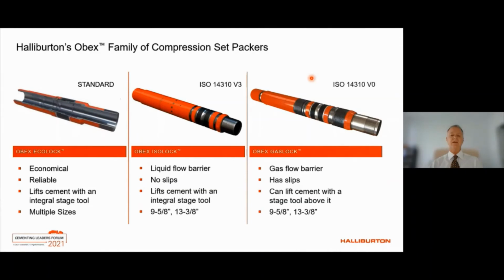V0 testing is a bidirectional gas test incorporating axial loads with temperature cycling to ensure the tool provides a bubble-tight gas seal. In contrast, V3 is a liquid test incorporating axial loads and temperature cycling.